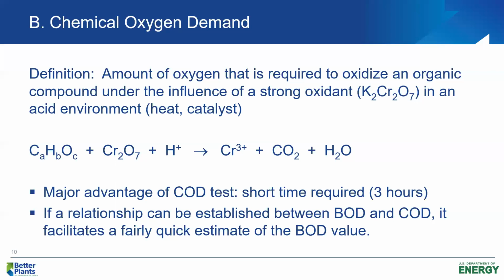It takes us 5 days to get a BOD5 result. We can measure the COD in about 2 or 3 hours, and so we can get a much quicker estimate of the organic content of the wastewater. But normally, again, we're more concerned about BOD.